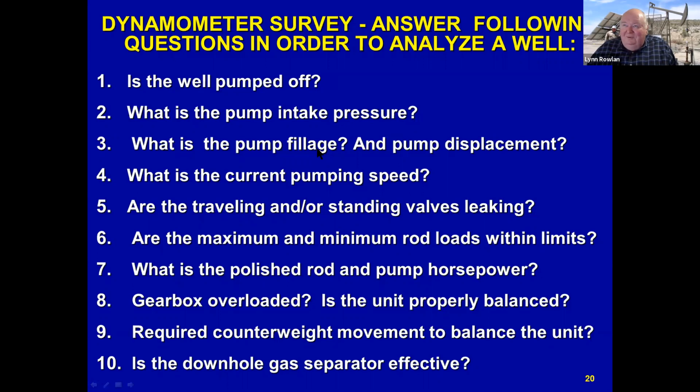We adjust it for slippage. We adjust it for free gas in the pump. And we can calculate an adjusted pump displacement and tell you how many barrels of liquid should reach your tank based on your dynamometer and output collection data at the well.